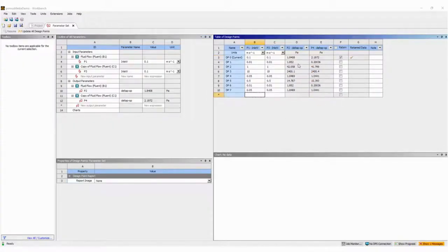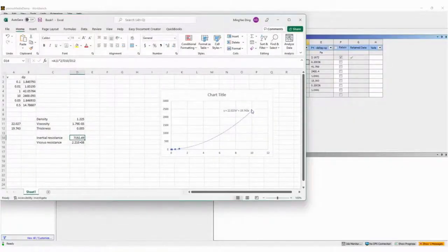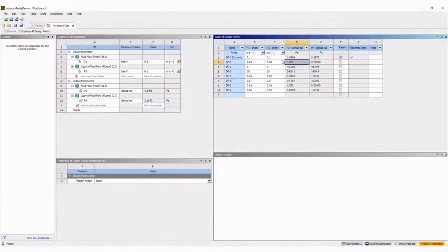Okay, I ran the simulation a couple more times here, got a few more points. You can see that at high flow rates we're getting a really good match, but at low flow rates we have less accurate predictions of the performance. That's probably due to the way we're doing the curve fitting. We may have some error down near the end here. So to get more accurate performance at low flow rates, we probably want to have more points there.